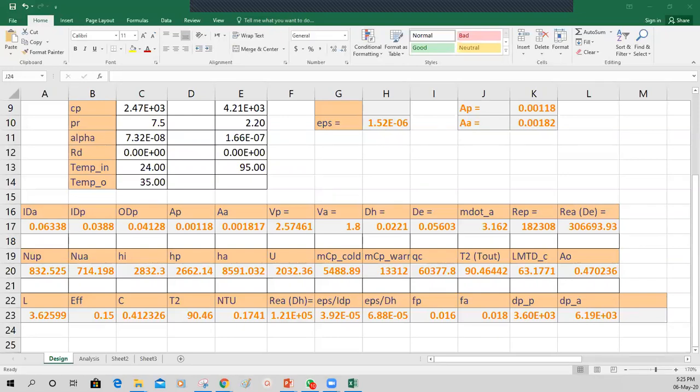So if you are using running water, for your flow rate, what was the flow rate? Just give me a rough estimate. 90 centimeter cube per second. Okay, 90 centimeter cube per second is your flow rate. Let's say you are having a line heater. Line heater means that your water is heated up immediately. So this much is the flow rate, multiplied by Cp and multiplied by the temperature difference. Do you want to increase the temperature by 10 degrees or what?